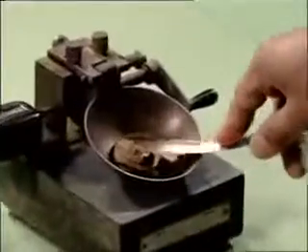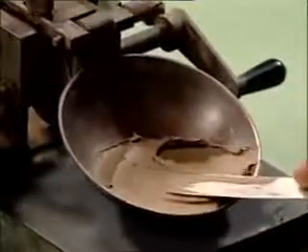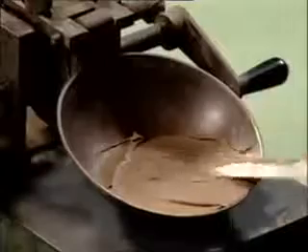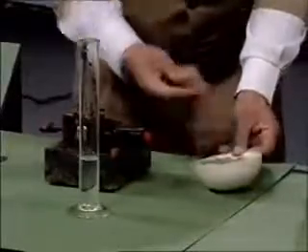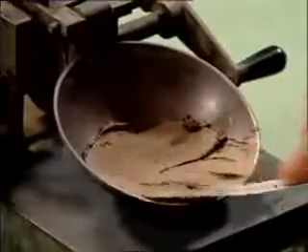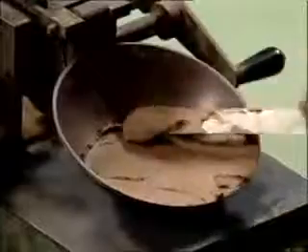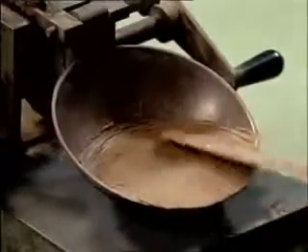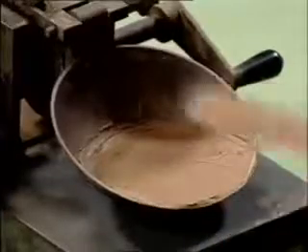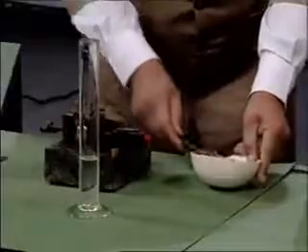Now, place a portion of the paste in the cup of liquid limit device. Squeeze down and spread the paste in the cup with the spatula. Trim the soil at the top so that the maximum depth of soil in the cup is 1 centimeter. Transfer the excess soil to the dish.